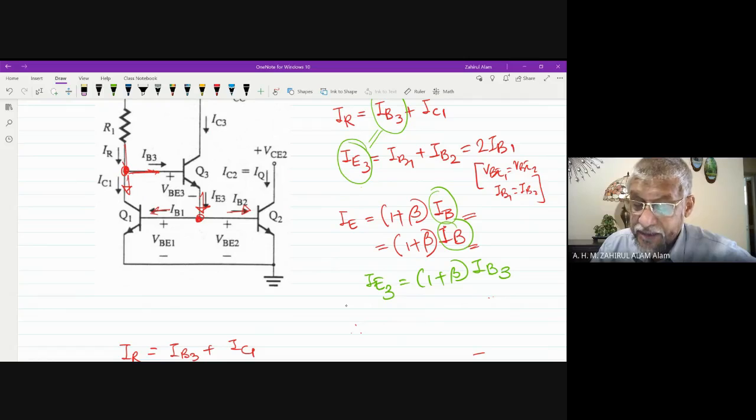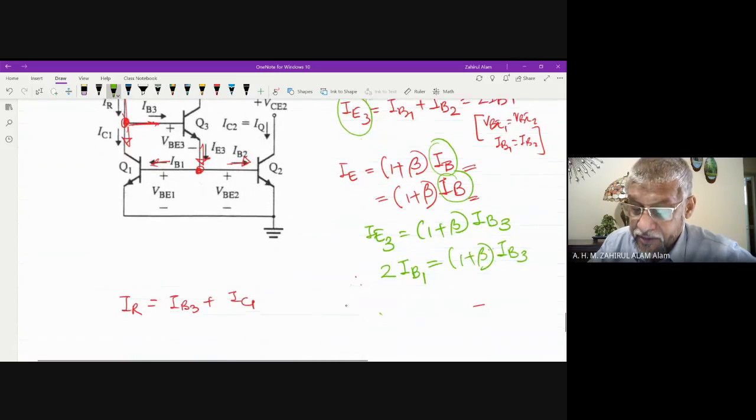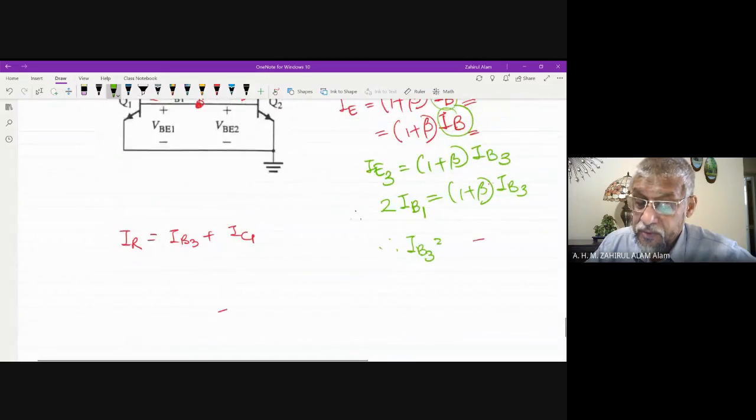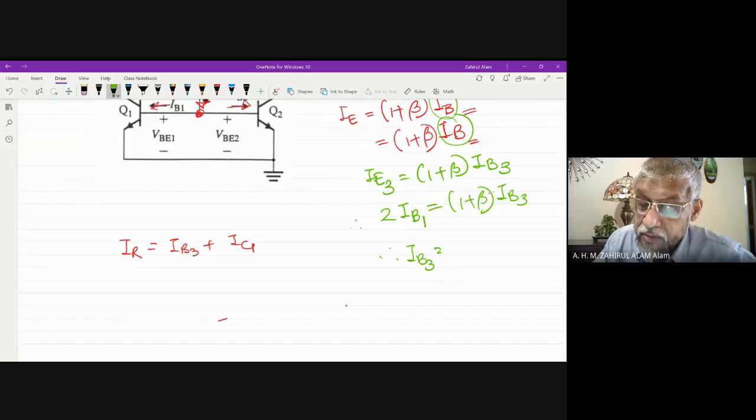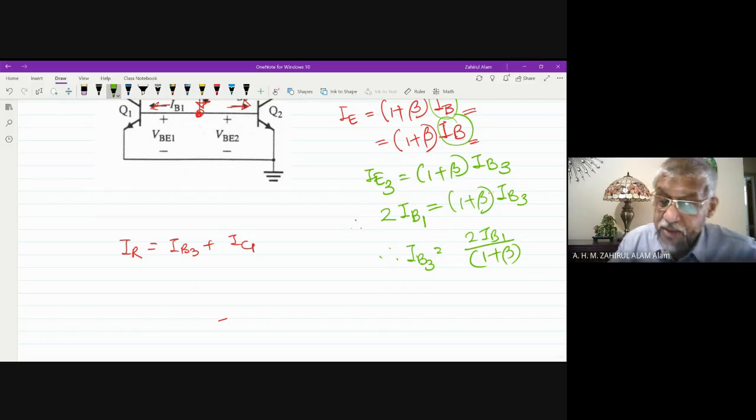So now IE3 is equal to how much? IE3 is equal to 2IB1, which is equal to 1 plus beta times IB3. So therefore, IB3 equals 2IB divided by 1 plus beta. Now matching my...